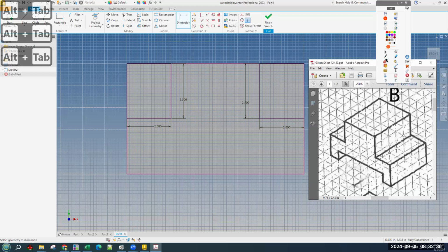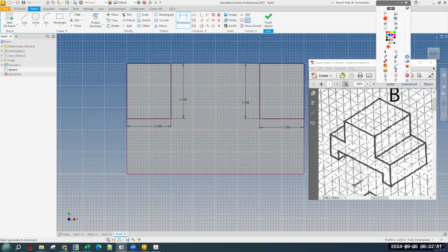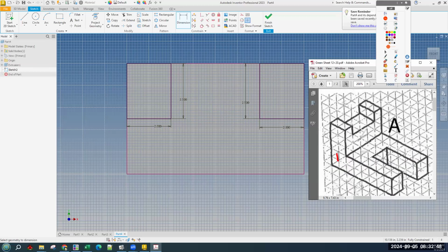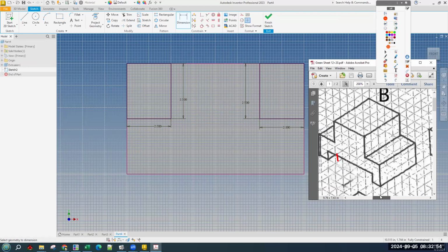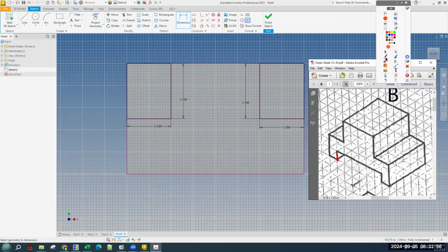And we could do finish sketching, cut extrude that, but like I said, I might as well do it in one move. The bottom part, it's just like the notch on the last one where we made a rectangle that was a given size, but then we had to dimension its location, its distance from the side. And that's what we're going to do here. We're going to make a rectangle that's 1 tall and it's 6 wide. So 1 by 6, but then we need to tell it that we want it to have an offset of 1.